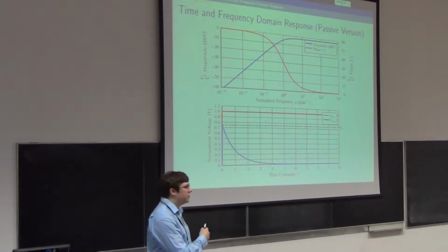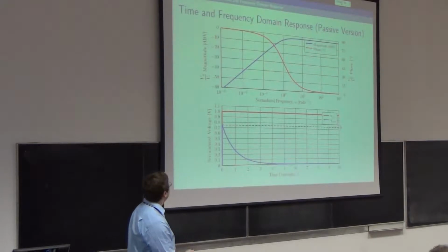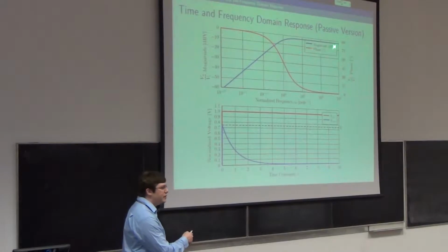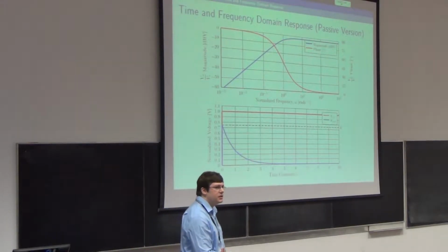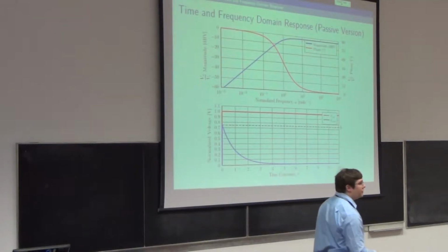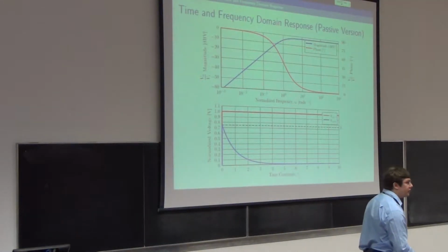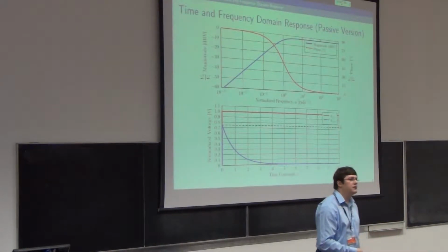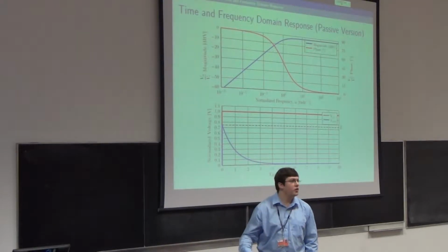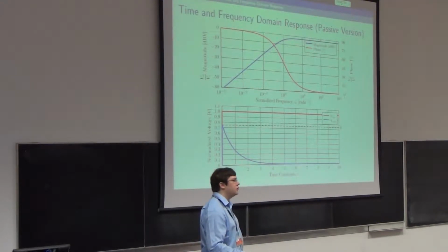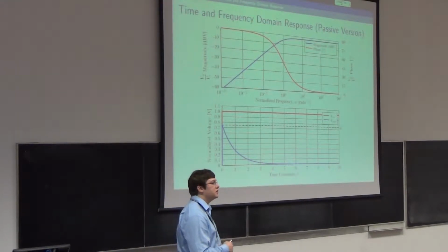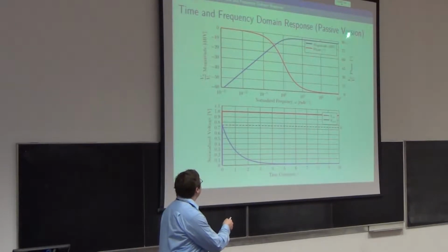So this is a standard high-pass first order arrangement. In this case we have a rise up to a maximum, which is K. So K is the frequency independent gain. It's not necessarily the DC gain, although if you have a low-pass system, the frequency independent gain and the DC gain will be the same thing. And if you have a high-pass system, the frequency independent gain and the gain at f equals infinity, that's infinite frequency, will be the same. So K is not necessarily DC gain, but it's the bit of the gain which doesn't change with frequency.